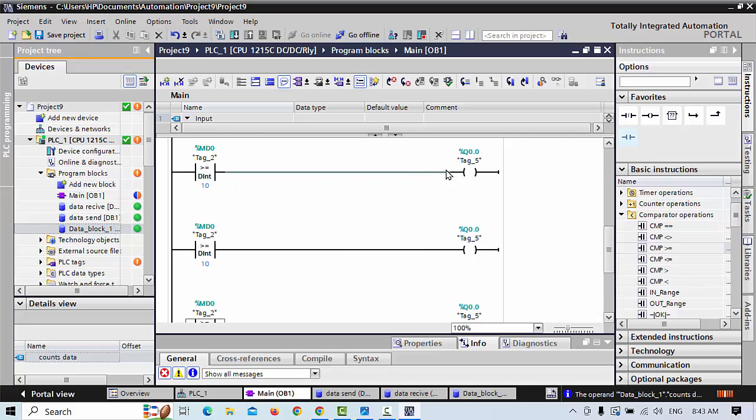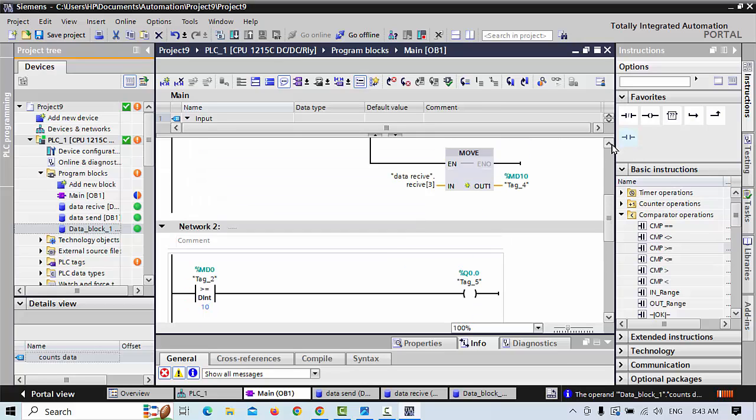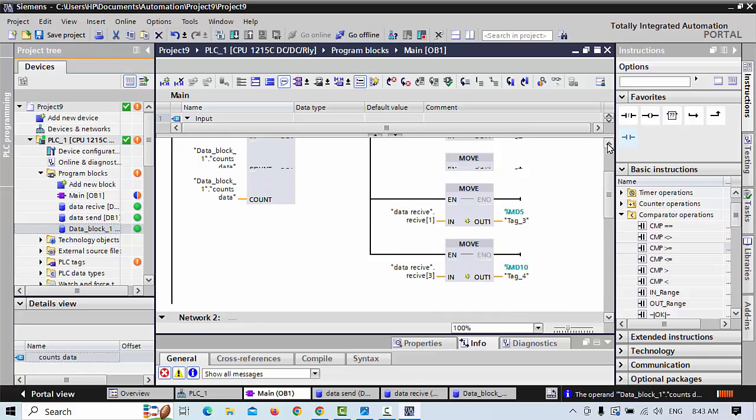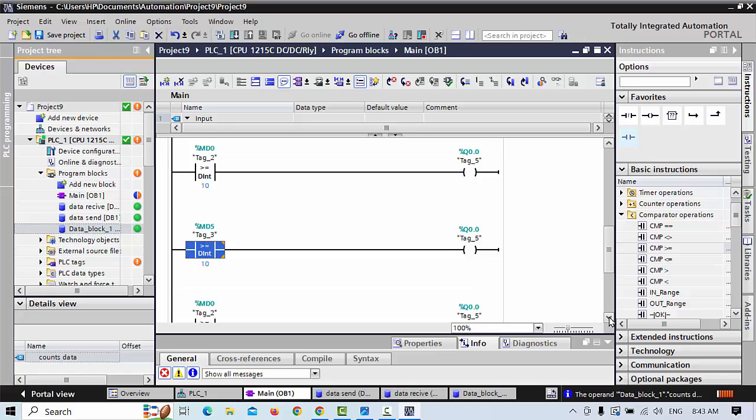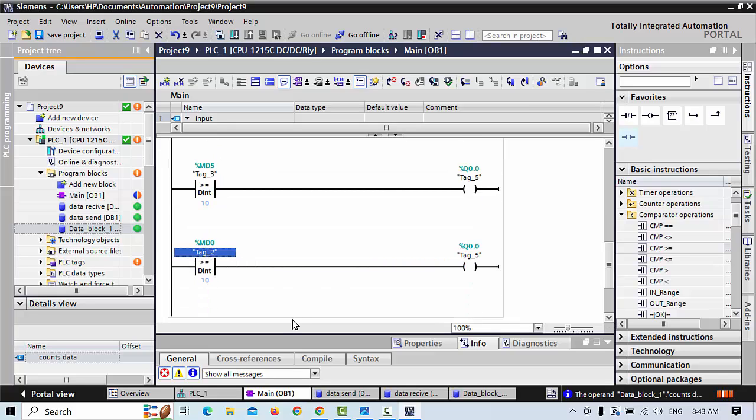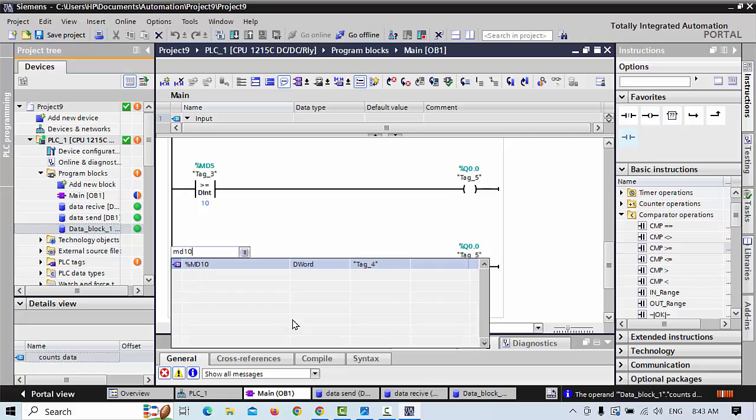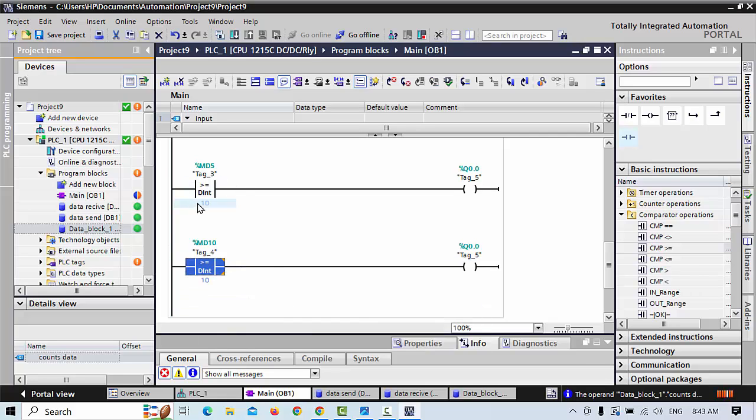That MD0 I will start one my coil Q0.0, and that I take MD, what data do we take, MD5 I think. MD5 we will check upside how many data. MD0, MD5 and MD10 we take as the different data registers and we will use them here. MD10, and these values I will give different values. I will give here 20 for example, and here I give 30 for example.